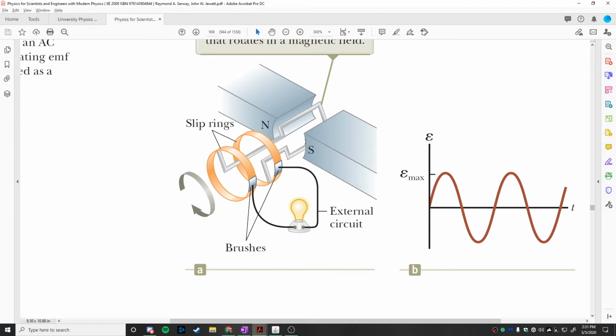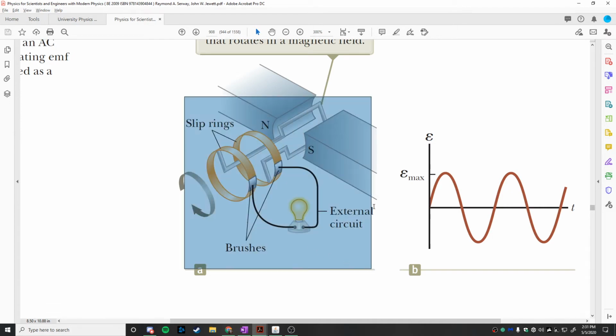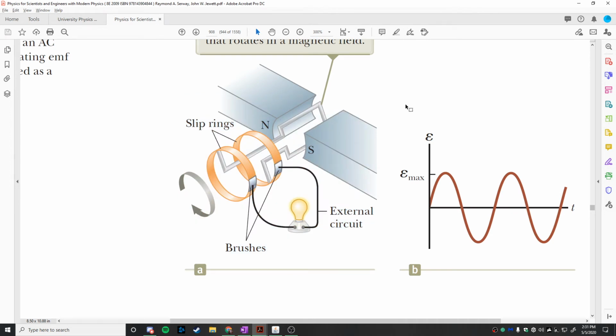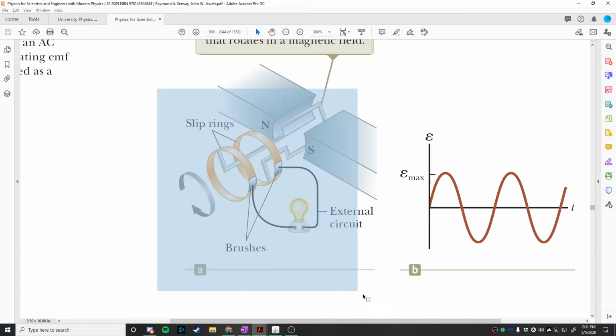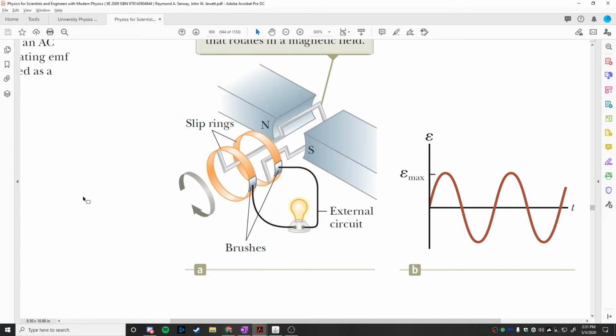So what do you have to do? Your forward force has to be equal to the backward force, and then you will move at a constant speed. This is basically the same idea, except with EMF. There's going to be an input EMF and a back EMF. The back EMF is like the drag force, or the friction force. Do you guys understand that? So there's going to be a constant speed that the motor will operate at.